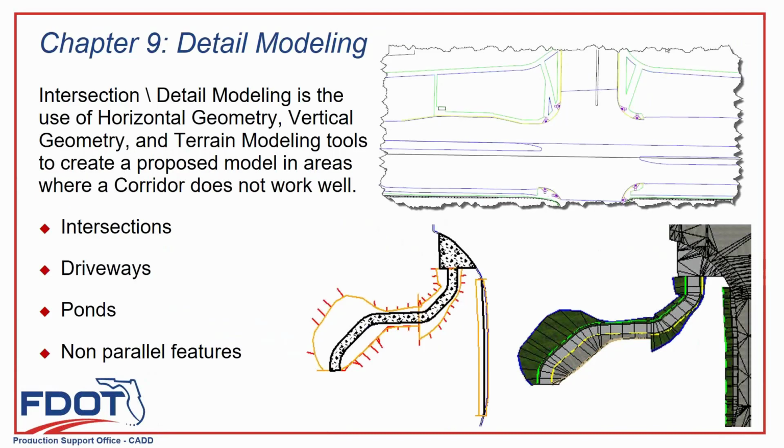There are other things, like when, let's say you've got two corridors and two slopes coming down, right? They're both searching for the existing ground. You want this one to tie to this one, and then you want this one to stop. But you can't get it. There's a corridor dependency issue going on here, right? You can't search for this line until this line solves. And then once you find that, you want to turn around and say, now this line needs to stop at this line. So we have techniques for finding the seam and having them both search for the same location.